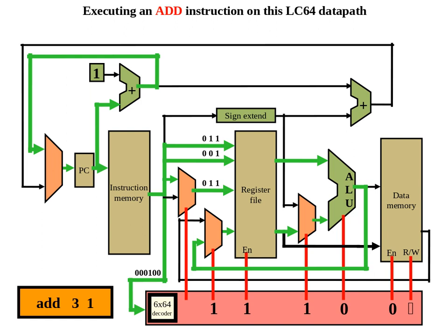A couple of other things I did not talk about though. Notice that these bits are your opcode, which is going to that decoder we talked about. In our finite state machine for the coin machine, we had a 5x32 decoder. This is going to be 6x64. Why? Because we have 6-bit opcodes, so the inputs are 6 different wires, and then by 64, because there's 64 different lines that can pop out of here. Don't worry, Verilog is going to have a simple way to implement this. And then that'll activate which lines we come out, just like in our finite state machine.